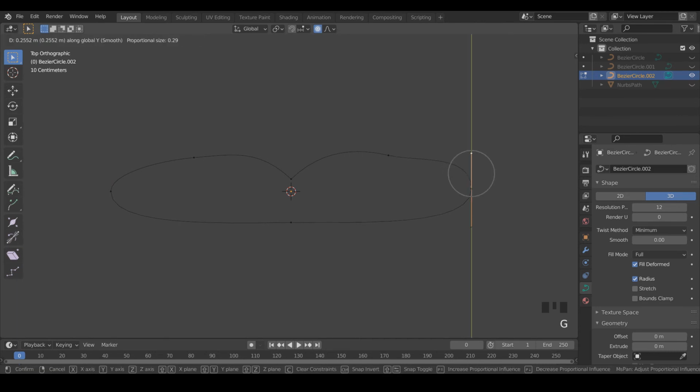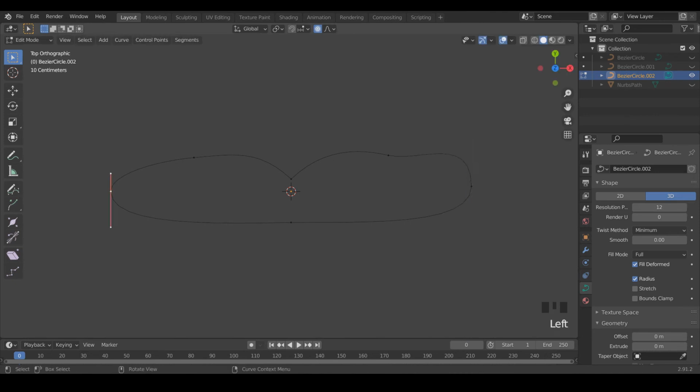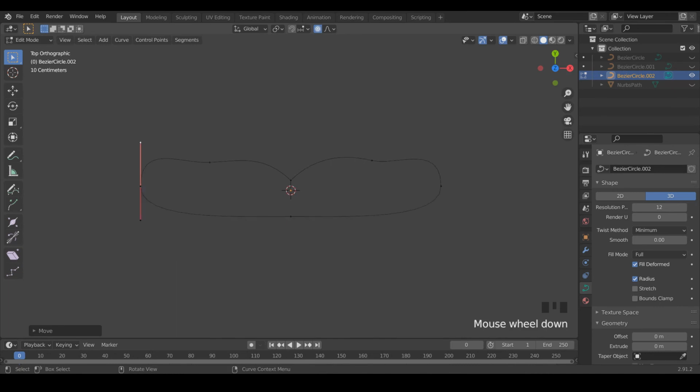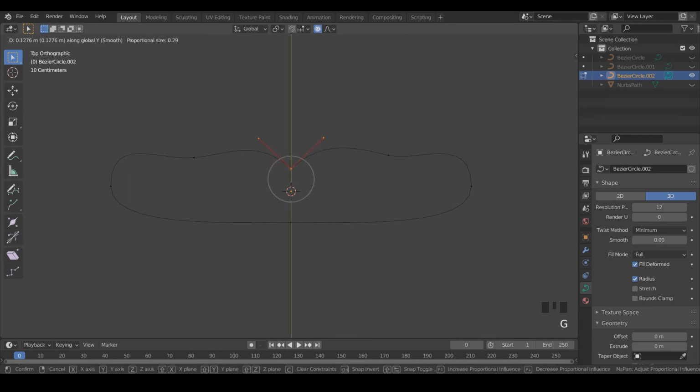And I'm just gonna adjust the handlebars on the outside vertices of these, and because they might be a little bit difficult to select both of them at the same time, I'm actually going to move them by typing in the values. Just gonna move this up on the y-axis 0.5, and then do the same for the other handlebar. Select G, Y, then 0.5. So that looks about right. I think I'm going to grab this center one, just move the whole thing up.